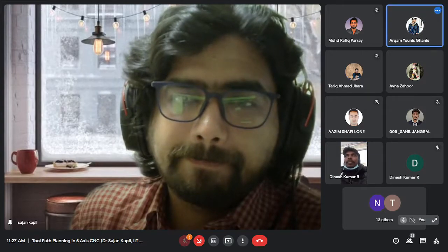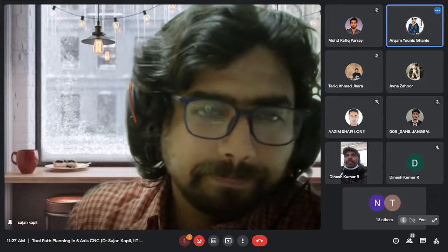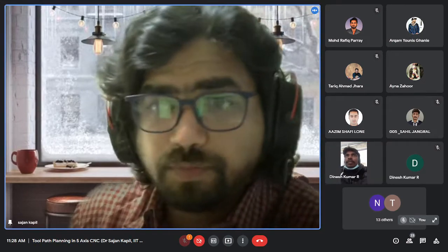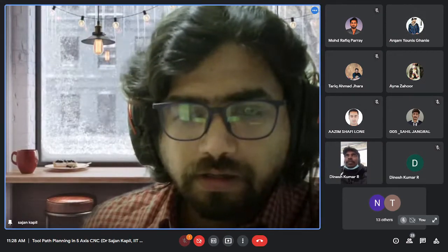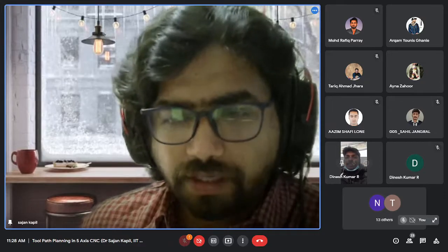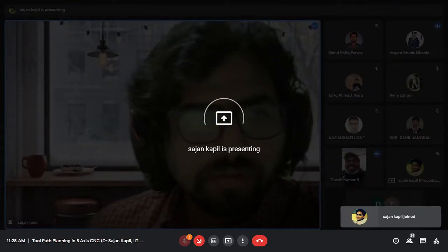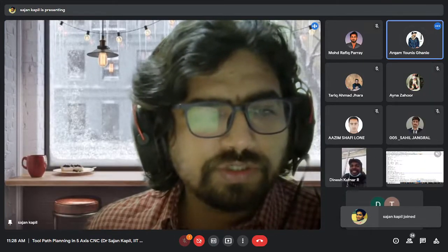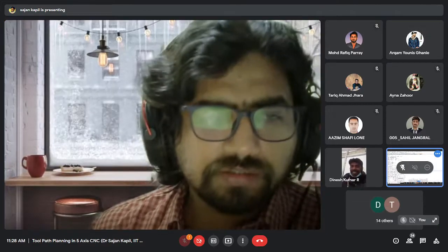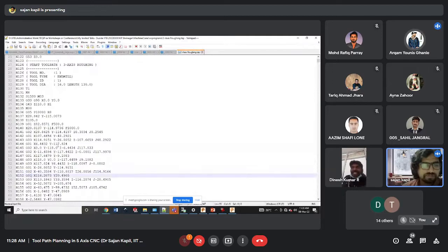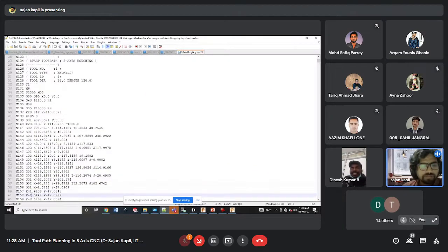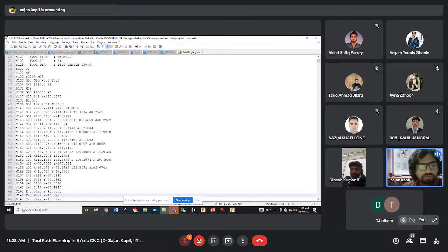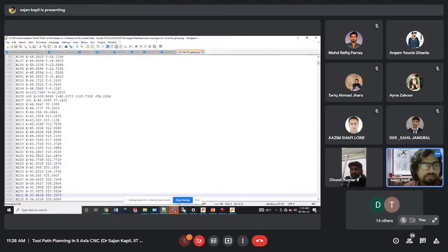Sir, I have a question, sir. You are not using any G code, M code in this program. Are you saying that there is no G code, M code? Okay, look here carefully. G codes are used once in the beginning only. You see that G01, G02, G03. Sir, it's already mentioned. Yeah, it's mentioned. I'm saying, once it is mentioned like G01, then it is not required to again write G01.